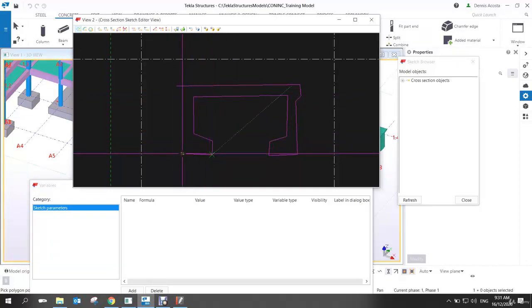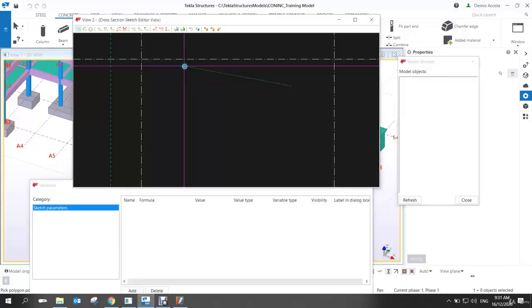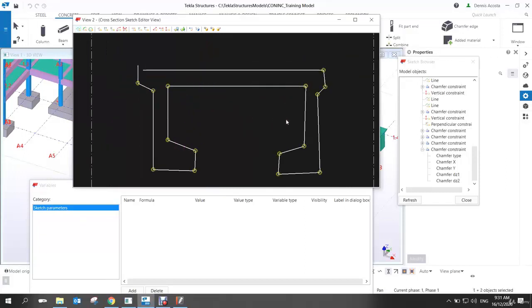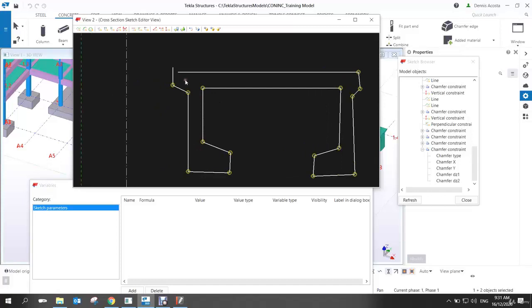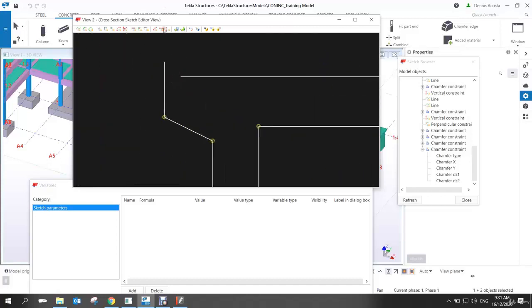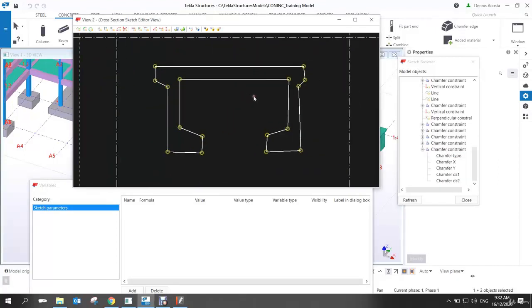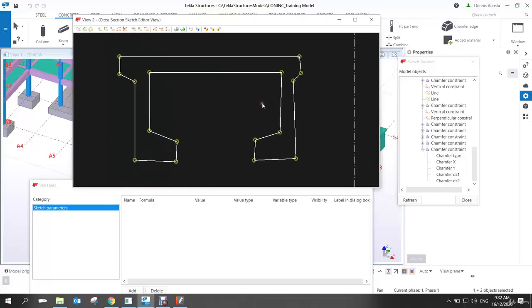So if you notice here, I'm just doing a sketch and then middle button of your mouse. So meaning sketch anything, any shape, but you can make it correct once you add the variable. So here, the next thing is you add this coincident constraint. Okay, add. What is fixed constraint? Fix this one, coincident constraint. Coincident.